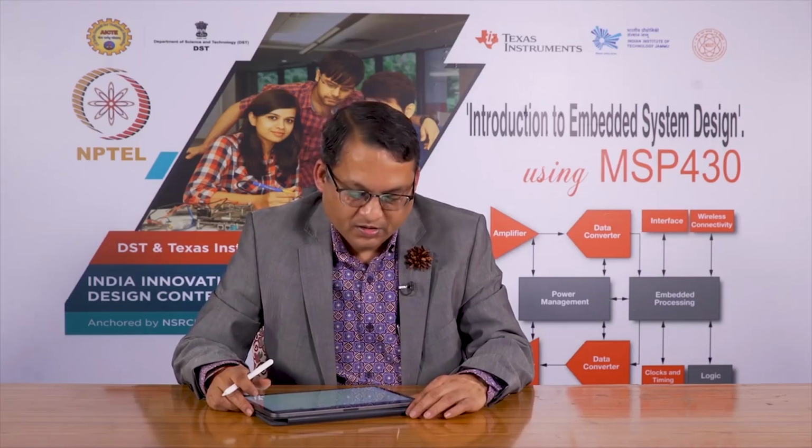If the supply voltage is more than the supply voltage of the microcontroller, you will have to use 2 transistors so as to isolate the higher supply voltage of the load from the low supply voltage of the microcontroller. So, with this we have seen how you can control external loads which may require higher current and higher voltage to be handled and controlled through a microcontroller. We have seen various topologies.